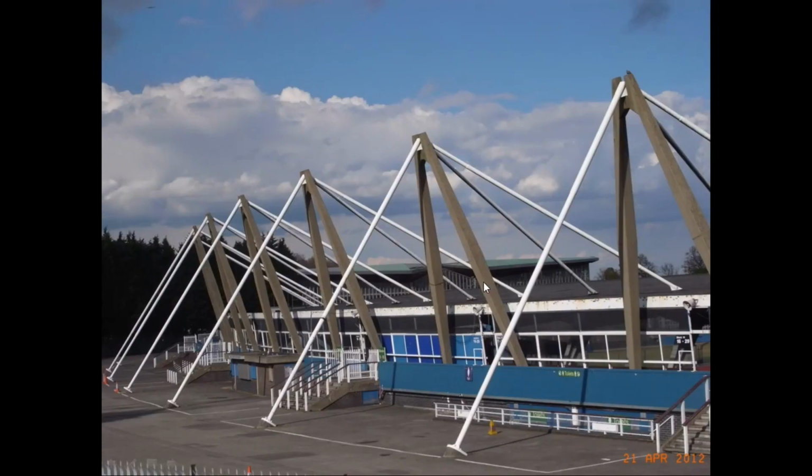Go back to the Forth Rail Bridge, the living model. These steel rods, tubes, I think they are rods actually, are in pure tension, aren't they? This is the big compressive element, and look again, it's not just one simple block of concrete with the same cross section all the way through. It's slightly tapering. And again, if you remember our very first slide of a column going into compression, as the load pushes down, it slightly expands on the outside. If you design that into the column, you're dealing with the forces right at the beginning.